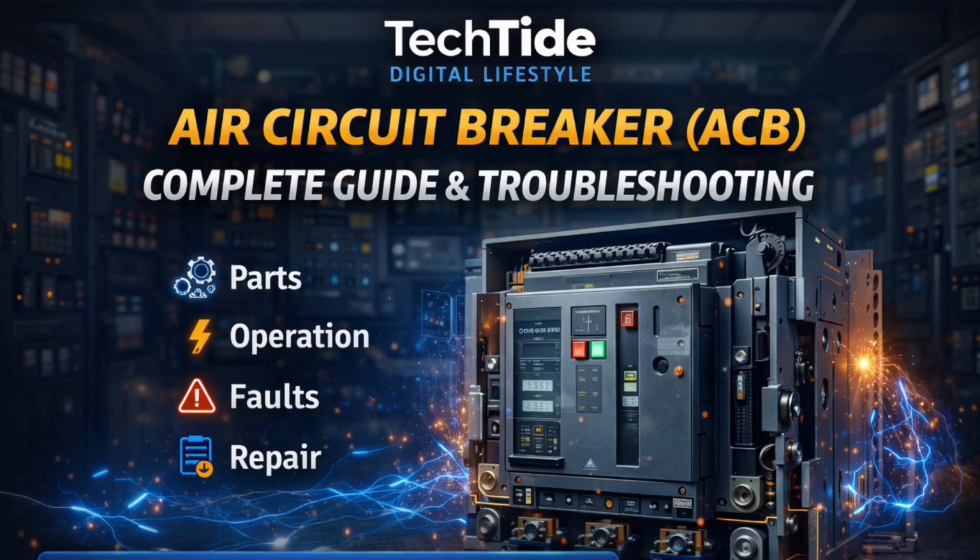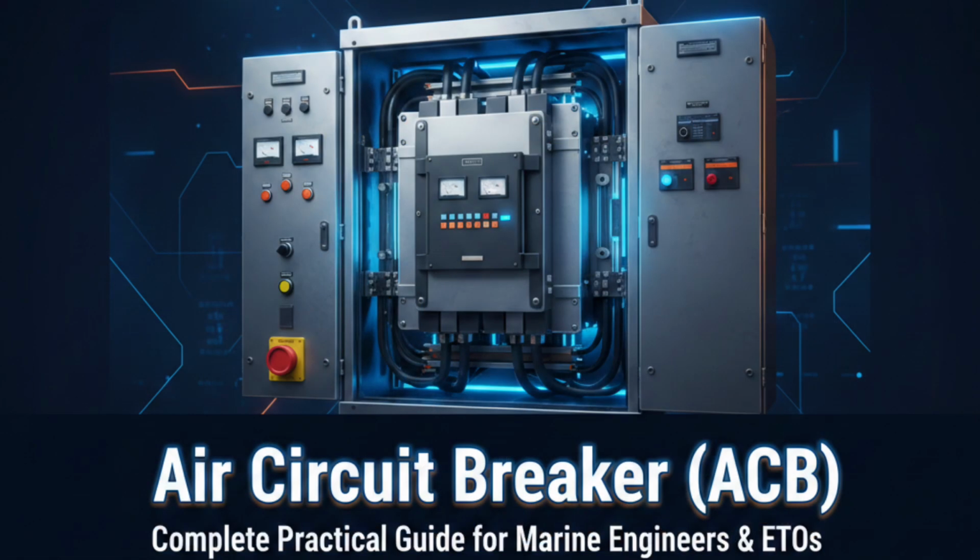Today's very important lecture, part of the tutorials series, is the air circuit breaker, ACB. On the screen, you can see a large air circuit breaker installed inside a marine main switchboard. This is one of the most important components. An air circuit breaker, or ACB, is a low-voltage high-current breaker used to protect generators, bus bars, and main distribution systems. It is called an air circuit breaker because the arc formed during tripping is extinguished in air at atmospheric pressure.